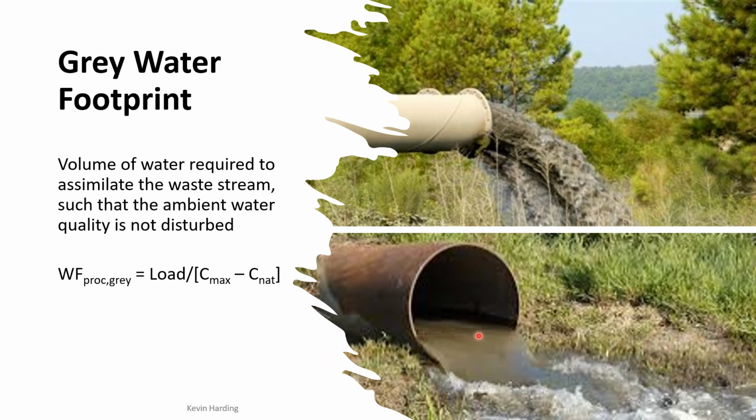If you have a blue water footprint plus the green water footprint plus the grey water footprint, that gives you the total water footprint for your site. In 99% of the cases I've come across, the grey water footprint, because of that virtual number that you're adding onto the side, always dominates this, depending on how you are setting the system up, but it almost always dominates.